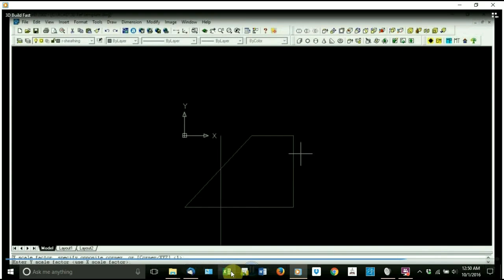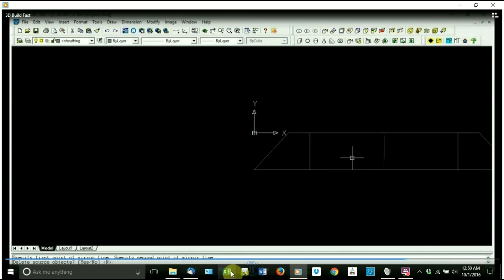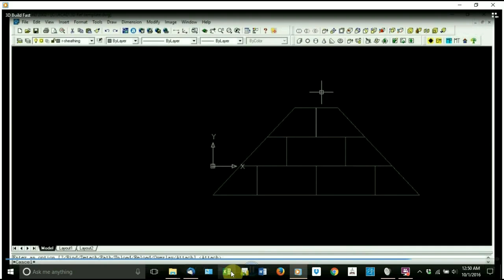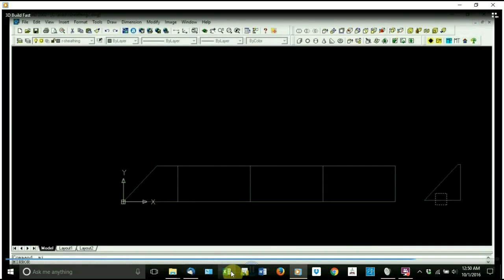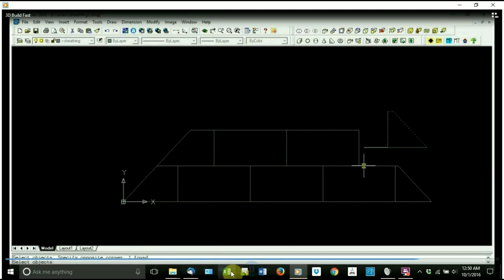And now it's doing the roof sheathing. And this is on the ends, so it'll be a triangular shape. And the way this is modeled is I'm looking directly at it, so I'm perpendicular to the sheathing. So when I put this into the building, I'm going to rotate the building 22.619 degrees about the x-axis. And so one of the faces of the roof is directly perpendicular to me, and then I'll place that sheathing on top, so it'll sit perfectly on top of it. The 22.619 is the angle of a 5/12 roof.